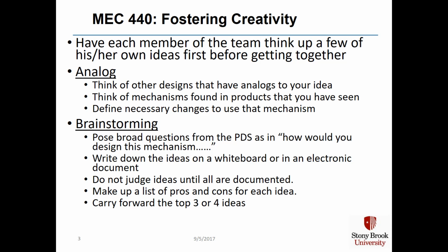A time-honored method for creating concepts is to think of other designs that have analogs to what you're trying to develop. What mechanisms do you need for your product? And what other products can you find this mechanism in? What changes to the mechanism will you need to use it in your design? For example, suppose you need a vacuum suctioning device in your product. Study a vacuum cleaner. How does a vacuum cleaner create vacuum?